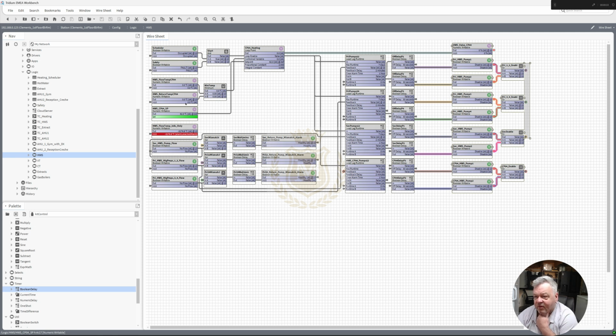The reason I've got the set point there and the loop is we've got a control valve that we need to open and close. So all I've done here is put the set point in there of 62 degrees, which is adjustable by the client. I've taken the minimum of the two temperatures, flow and return, put it into my control variable, my loop point, set the prop to 2, set the int to 1, and of course the loop enable is from the scheduler, and we're just using a lead lag runtime.